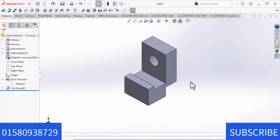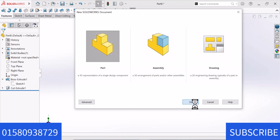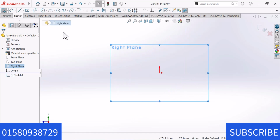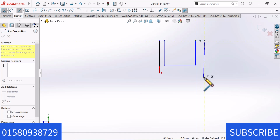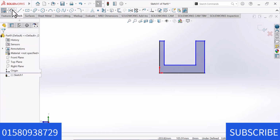Okay. Now I am going to draw another sketch. I am going to draw slowly, if you want to easily learn this job. Now I am going to select right plane and sketch. Now draw the line from origin. Okay, select. Now go to Smart Dimension.